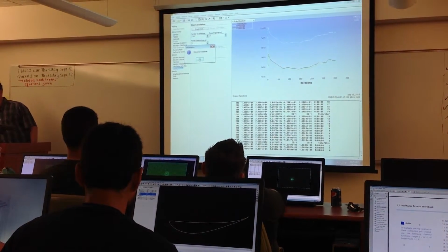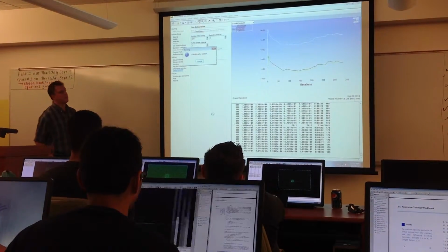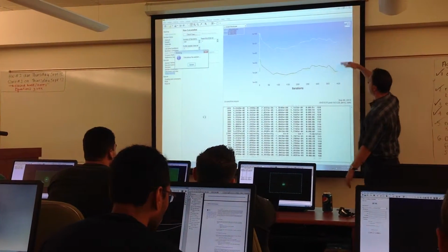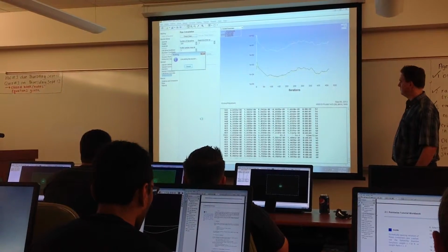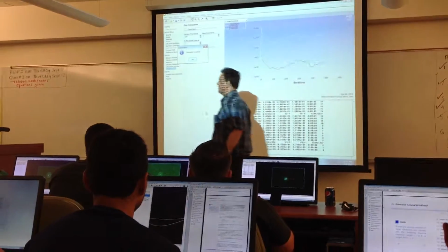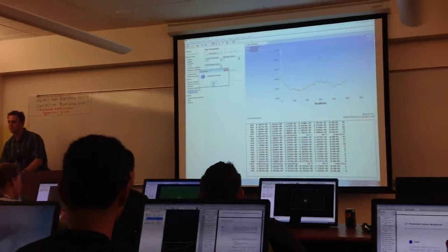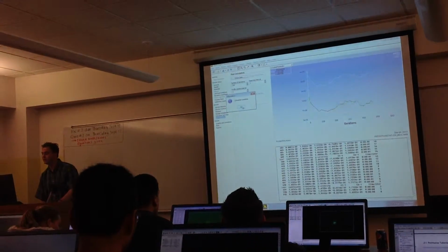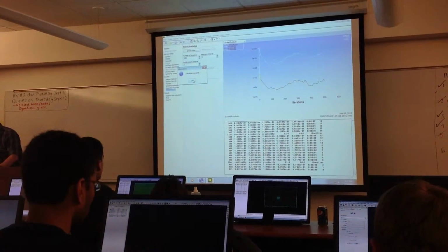Not a surprise. If you run laminar flow, it's going to be really hard to get any kind of solid convergence. The best thing is to run it out to the point where you see a plateauing behavior or a repeatable behavior. This is what we're up against here. This is 500 iterations, and it's not going to converge.